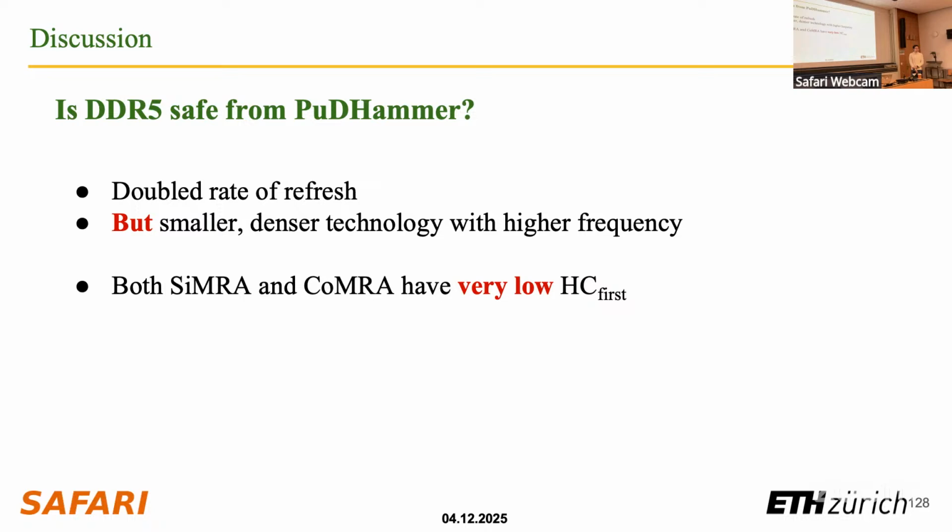So for example, flipping 1 to 0 is much easier than flipping 0 to 1. But when you do double-sided RowHammer, usually it's 0 to 1. So it's exactly the opposite of RowHammer. It's close to RowPress. We don't know why. But we believe that this definitely needs a circuit-level, TCAD-level simulation to understand what's going on, because you're doing something fundamentally different, right?